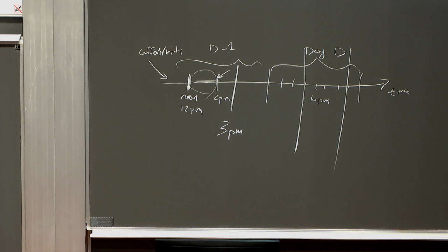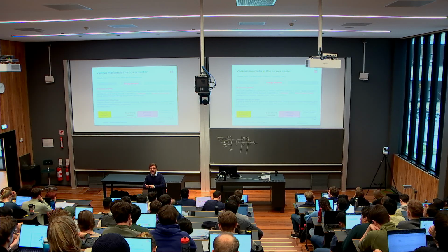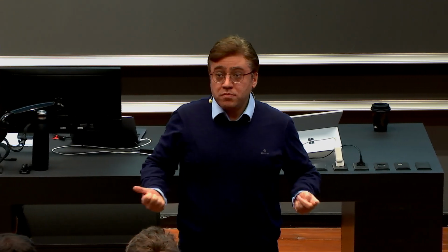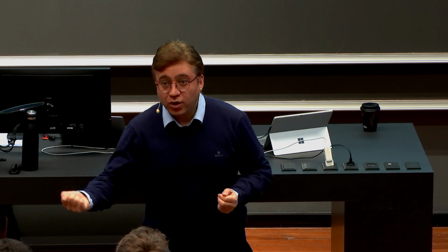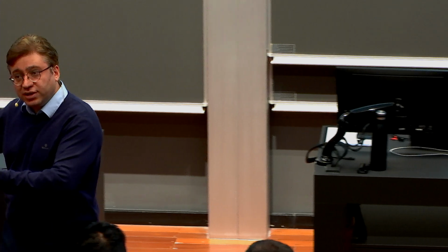Why? Sometimes, of course, you traded electricity in the day-ahead market, but now there are some reasons that you want to modify it. Maybe you have an updated forecast of your wind. Or if you are a retailer, maybe you have an updated forecast of how much demand you will have tomorrow. Or maybe you realize one of your assets is out for tomorrow. You just realize it after day-ahead market clearing. Or maybe you are a trader. You want to buy and sell and earn money. Then you go to the intraday market. Is it clear why we have the intraday market? Then you don't need to leave these changes to happen in real time.